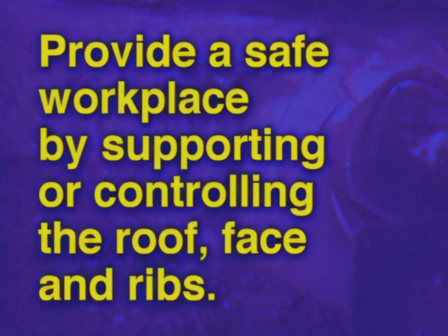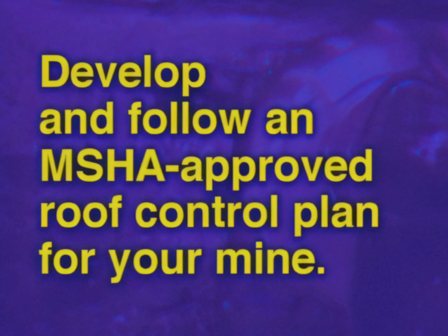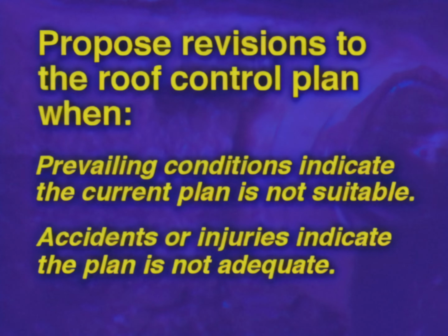If you're an operator, you must provide a safe workplace by supporting or controlling the roof, face, and ribs in areas where persons work or travel. Develop and follow an MSHA-approved roof control plan for your mine. Propose revisions to the roof control plan when prevailing conditions indicate that the current plan is not suitable, or when accidents or injuries experienced at the mine indicate the plan is not adequate.